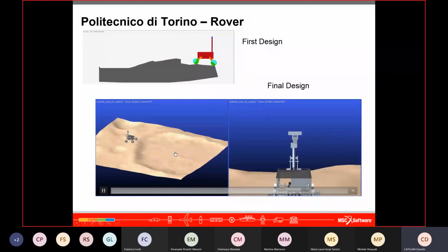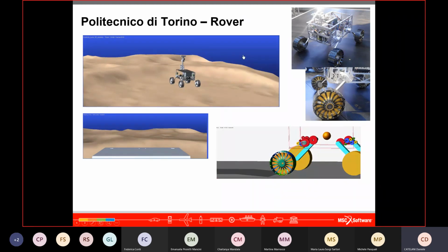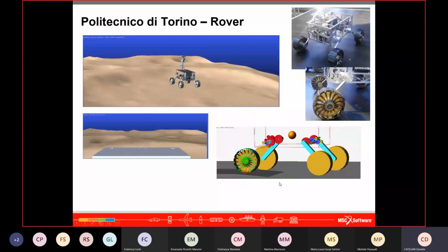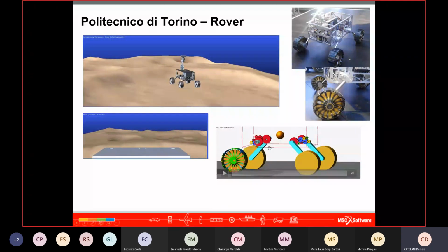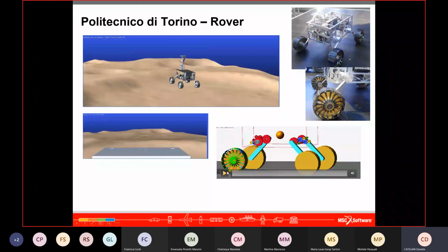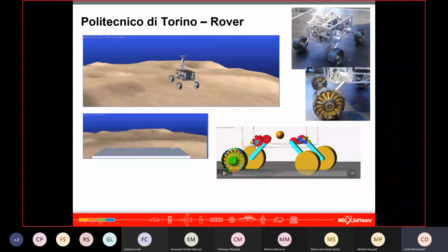And the logic of the control was changed in order to consider also this problem. The third student introduced the flexibility of the road, the wheel, because you have an obstacle. You see here the complex transmission system made by gears, cams, links, shafts, etc. If you have a problem during the contact and there is no dissipation of energy, the force of contact is transmitted completely to this system, and in this complex and expensive transmission system, you can have a failure.